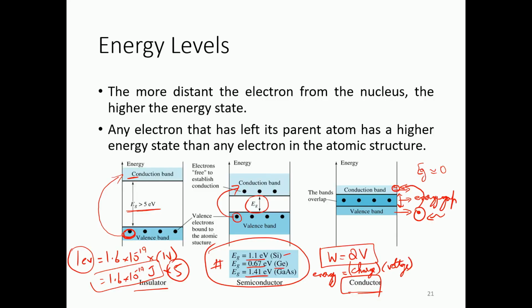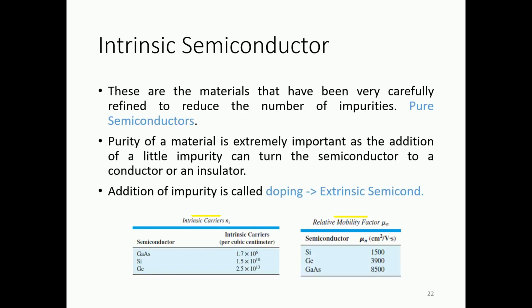So this is basically what is happening inside insulator, conductor and semiconductor materials. Whenever we want to create a semiconductor material with silicon, germanium or gallium arsenide, the energy Eg should be these standard values. In an insulator, we need a very high amount of energy, and in conductors the Eg value is negligibly small. That's why the electrons can easily move from one point to another. So this is how the energy levels work at the atomic level.